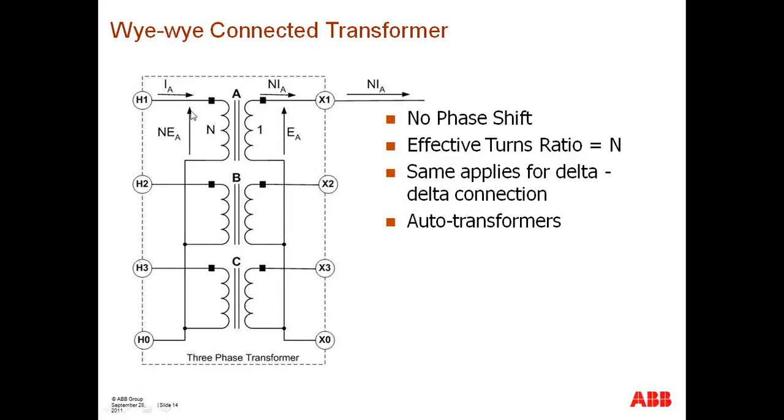And you can see that on both high voltage winding and low voltage winding, we have a connection where the polarity mark is connected to phase A on the system, the polarity mark is connected to phase B on the system, and the polarity mark is connected to phase C of the system. And then the non-polarity legs of each winding are all tied together and connected to neutral or ground. The same can be viewed on the secondary or low voltage winding, where we have a YY connection.